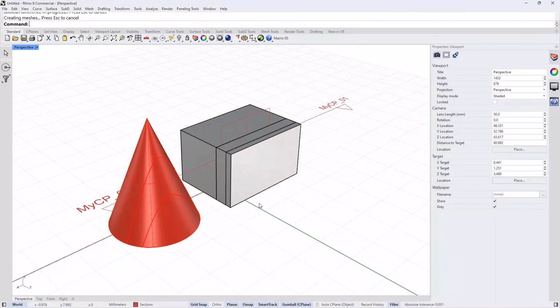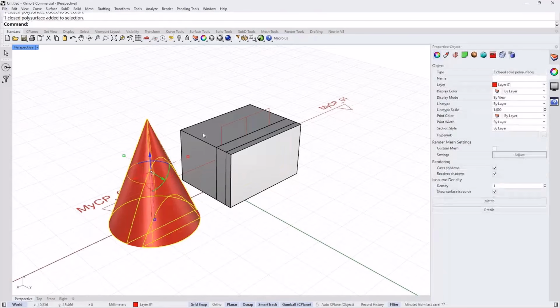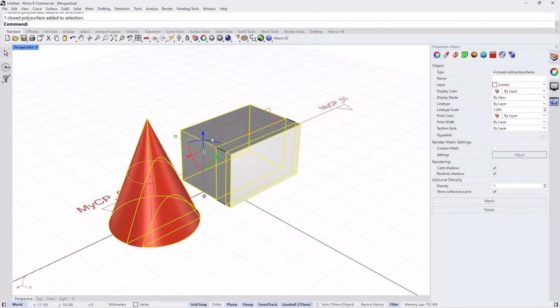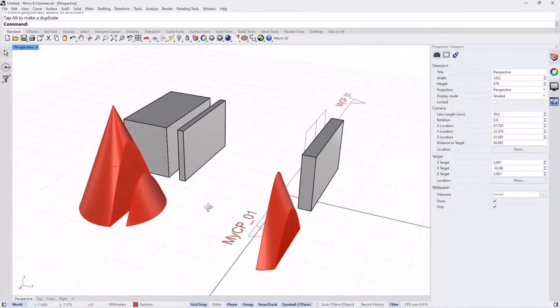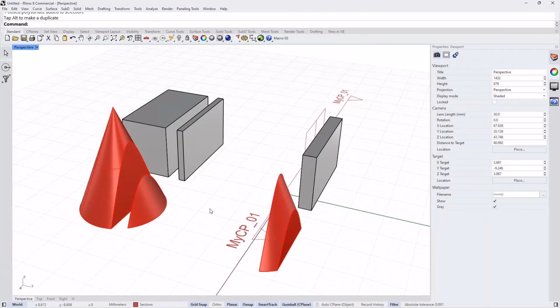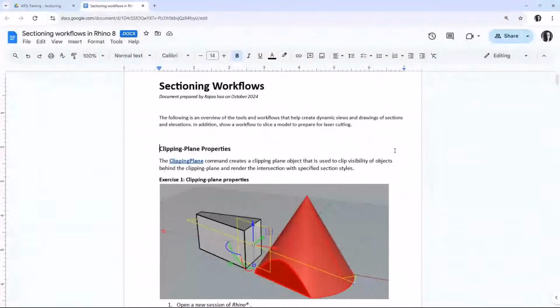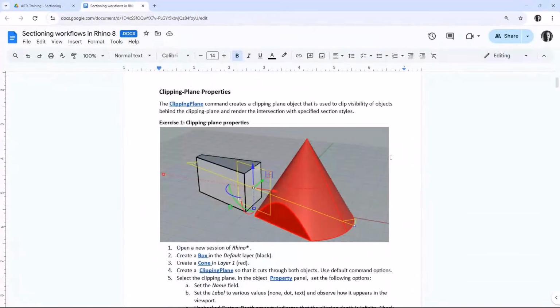And now let's just get that part, which is, like this was the original, but it's now all sliced up, if you will. But this is an actual modeling, right? Right now we are slicing out. There is an important distinction between when you're using clipping planes. This is for now just visual, but we use the clipping plane to extract a slice, and we use that slice to subtract it from the original model. And we can use the PDF. Let me get the PDF up there to just show you the parallels between what I've just done and what you can do to go through the exercise step by step.